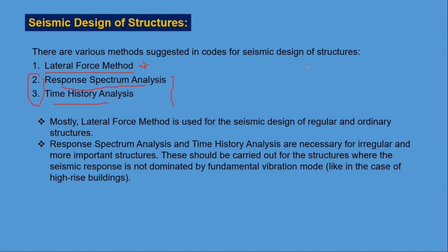Because if we draw the curve for linear analysis, it will be like this, but in reality, the curve should be like this. For a large load, and for the same deformation, if we draw the line, then we can clearly see that there will be certain extra forces included in linear analysis. That's why we take a response reduction factor to account for non-linearity of structures.